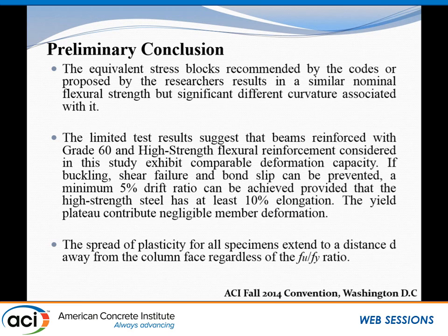So with that, I would like to conclude my presentation. The equivalent stress block recommended by the codes or proposed by the researchers results in a similar nominal flexural strength but significantly different associated curvature. The test results suggest that specimens reinforced with grade 60 and high strength flexural reinforcement considered in this study exhibit comparable deformation capacity.